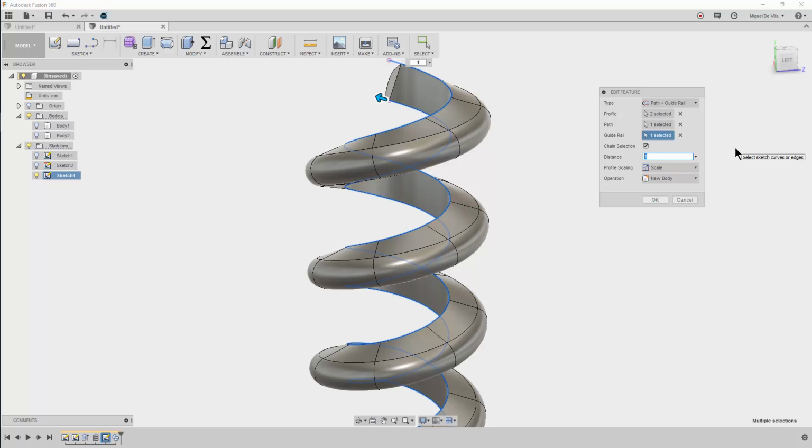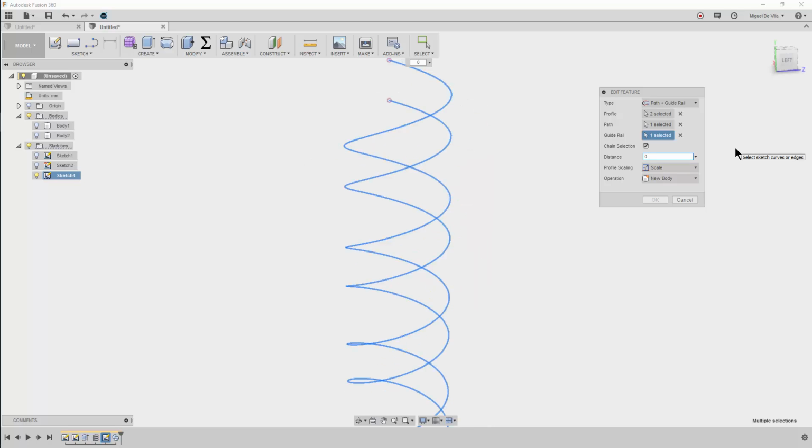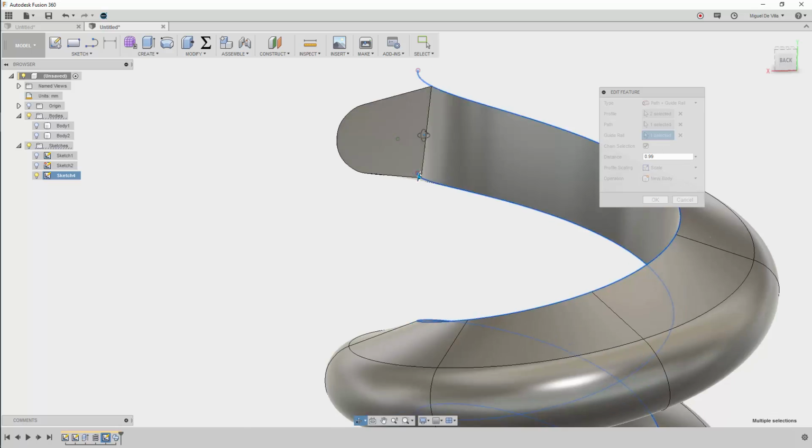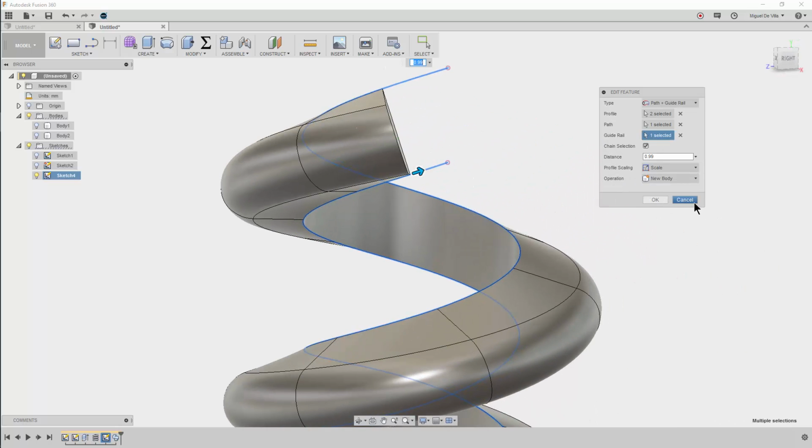One quick fix is to change this to like 0.99, just short of 100%. Apparently, this prevents the swept extrusion from having to fulfill the end conditions of the path, where it appears that it's having difficulty reconstructing. So, handy little tip, and now you know why and what this does based off of the last few minutes of the video.